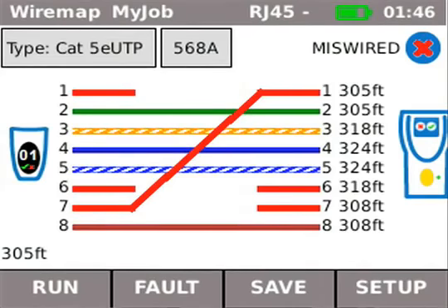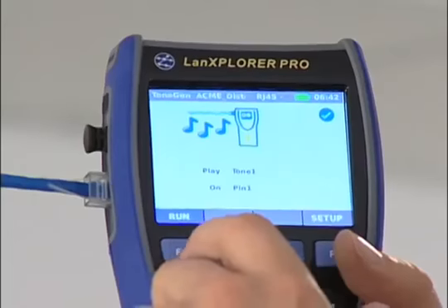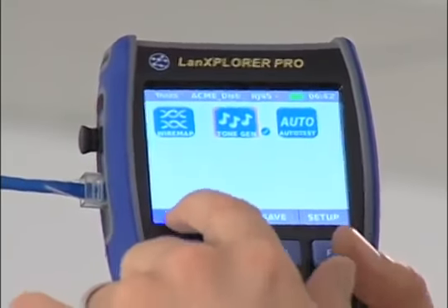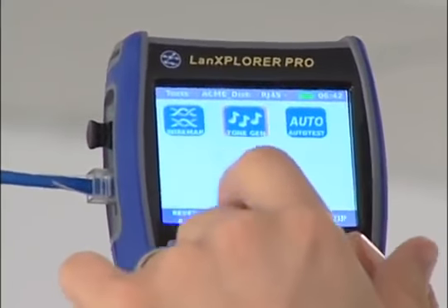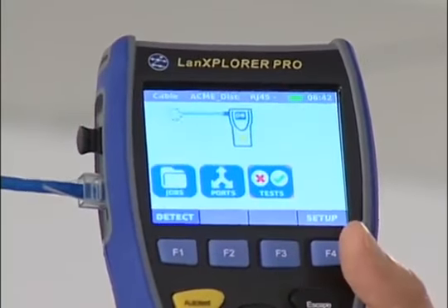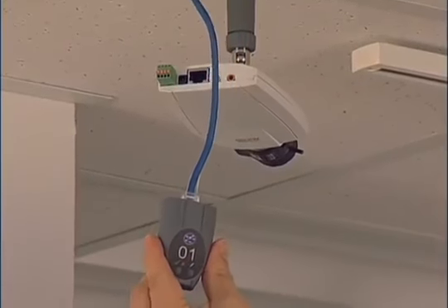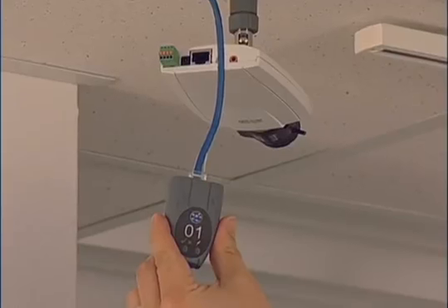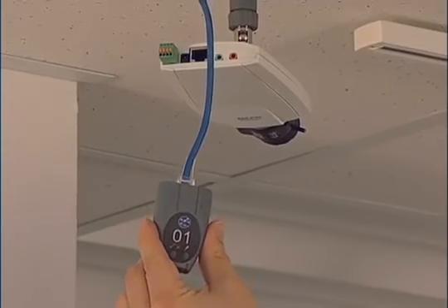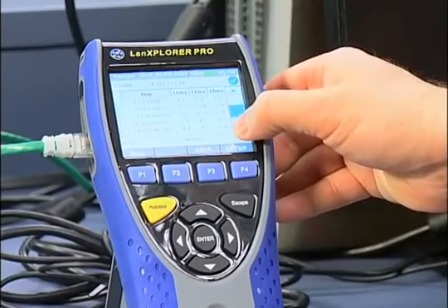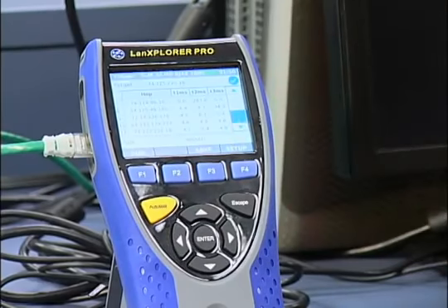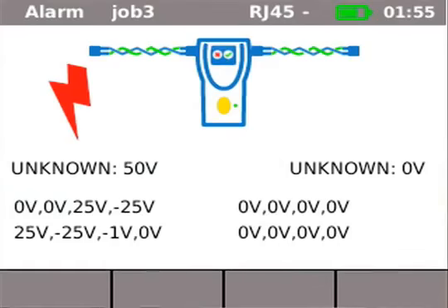For copper wire map testing, the cable test mode can perform detailed analysis with TIA 568 A/B coding and fault finding. And the LanXPLORER tests pin by pin versus pair testing to accurately depict even complex wire map errors. The integrated TDR measures cable length and provides accurate distance to shorts and opens in the cable. There is also built-in voltage protection that prevents damage caused by accidental connection to non-Ethernet outlets by emitting an audible alert and a display of voltage present on each pin.